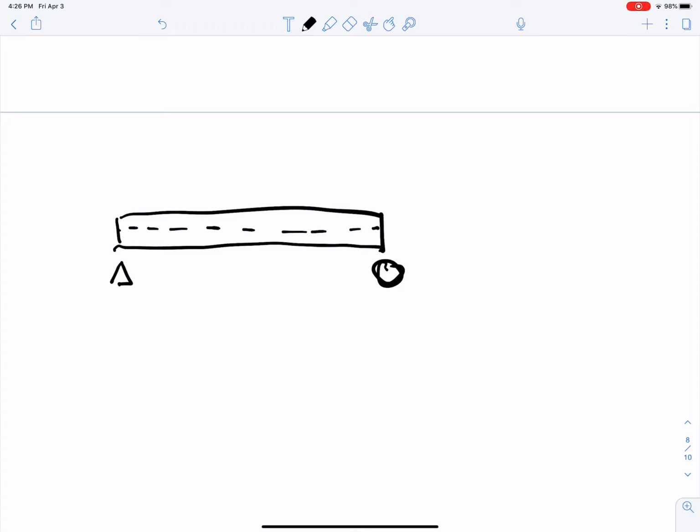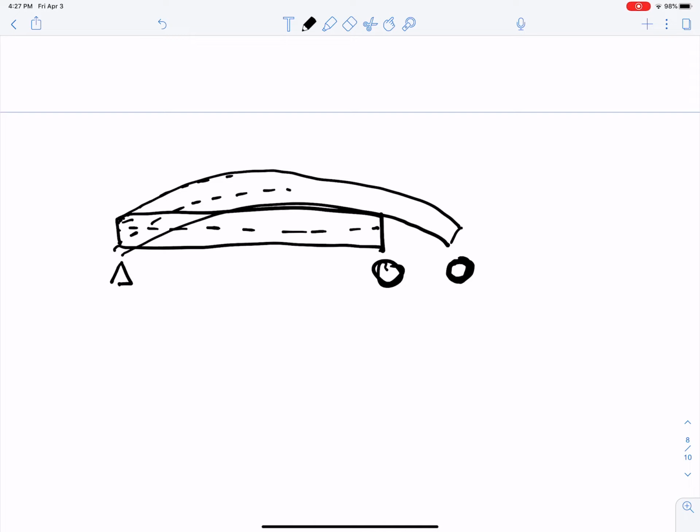Okay. This is the medial axis, the central axis. Application of delta T central results in movement. Supposedly it's positive, then the bar would move to the right. Application of delta T to the top and to the bottom could result in the development of curvature. So you may end up in a situation like this.